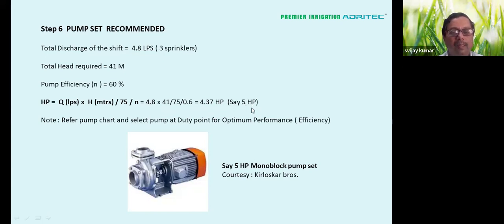For example, you also have to select your pump in such a way that it gives optimal performance, which we call the duty point. I had explained this in another webinar: when you have the head versus discharge, at the point where the efficiency of the pump is the highest, that is generally the mid range. So please select the pump in that particular range. And courtesy of Kirloskar Brothers, I have selected a 5 HP monoblock pump set, which is actually going to serve the purpose. And this is how it is going to work.